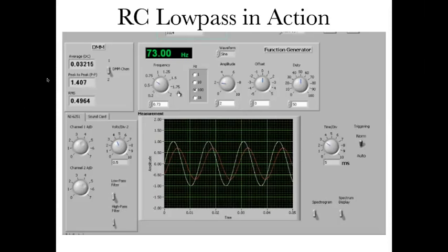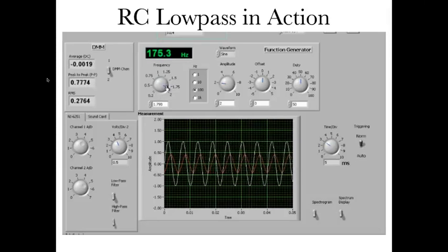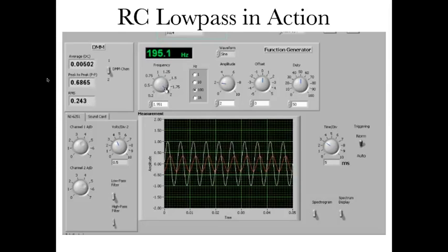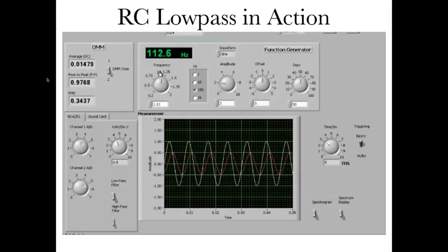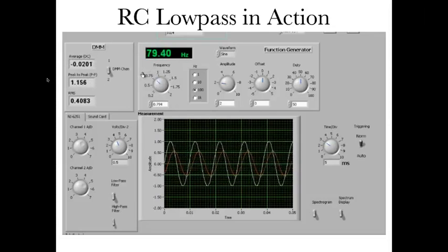Original frequency, and I'm going to vary it continuously now so we can see it go up in frequency, so the amplitude will be going down as the frequency goes up, just as predicted. The phase shift keeps increasing, getting more negative. And then if we go back the other way, we see the amplitude go up and keep going down, down, down in frequency below the cutoff frequency, well inside, and it looks more and more like the input.